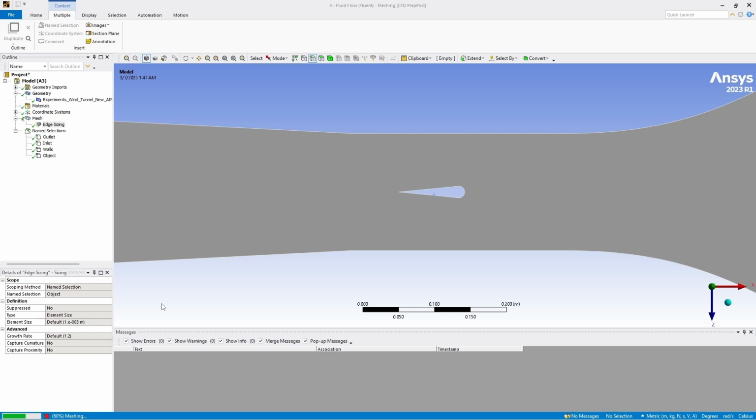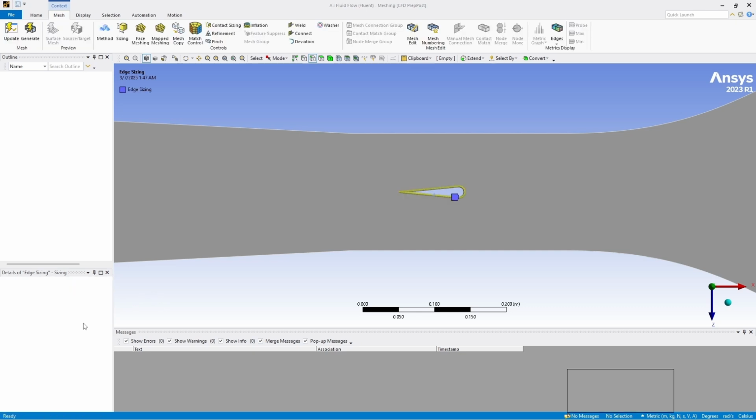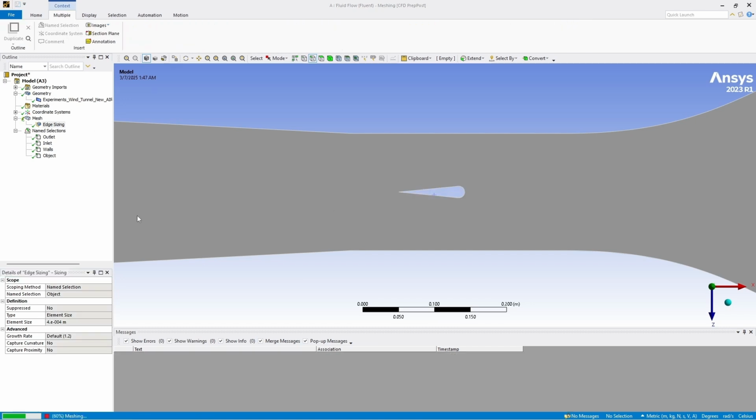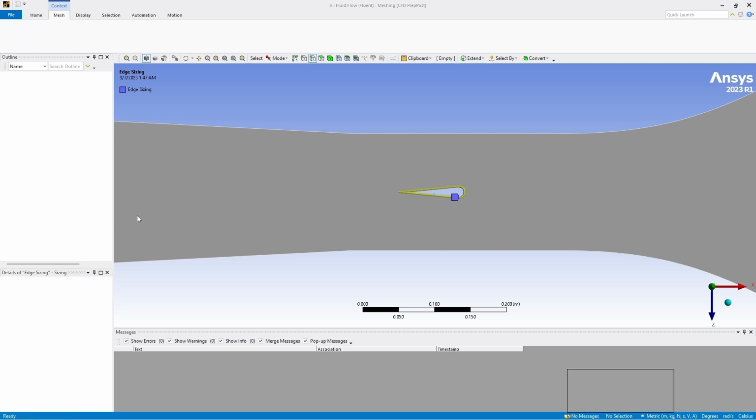So what we'll do instead is use something like edge sizing, where we're going to grab an object. Usually in 3D, you could make a cube or some type of geometry, and then select that area to refine that mesh and make that element size smaller than the outside geometry. So here you can see I lower it to 0.0004 meters, and once it's just done meshing, I'll show the whole mesh completely and how it sort of refines around the edge so we get more of a clear understanding of what's happening on the surface of this guy and around it.